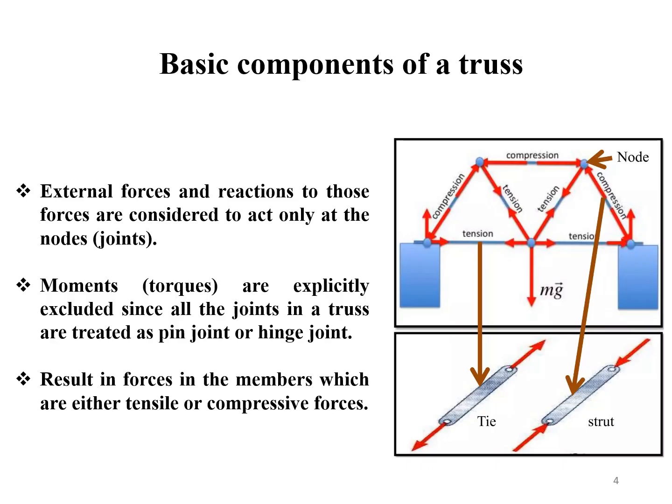Because all joints are pinned, the members cannot carry bending moments. They can only carry axial loads. This simplifies the truss structure analysis. For a truss, each member is either in tension or in compression.